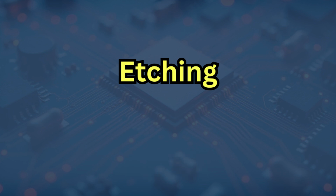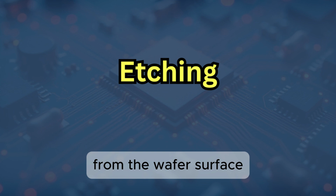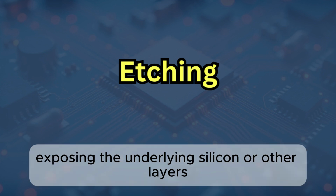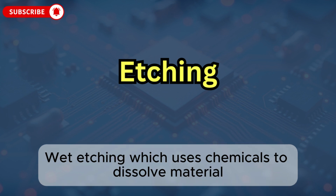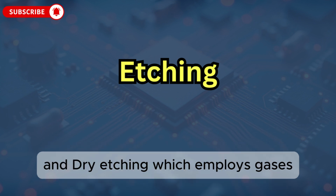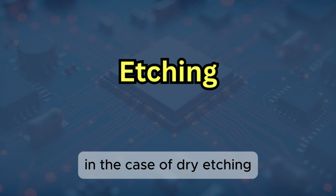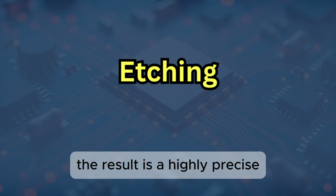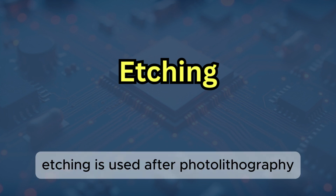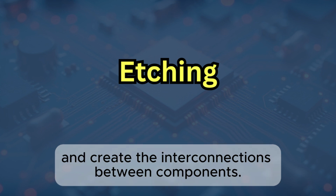5. Etching. After doping, it's time for etching. Etching is used to remove unwanted materials from the wafer surface, exposing the underlying silicon or other layers. There are two main types of etching: wet etching, which uses chemicals to dissolve material, and dry etching, which employs gases to etch patterns in a plasma environment. In the case of dry etching, materials like argon or chlorine-based gases are used to etch fine patterns into the wafer. The result is a highly precise, cleanly defined structure. Etching is used after photolithography to carve out the active regions and create the interconnections between components.